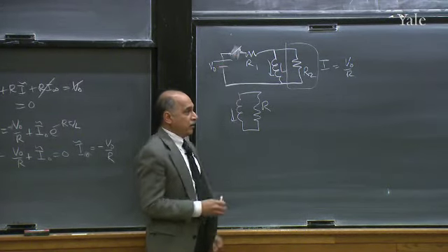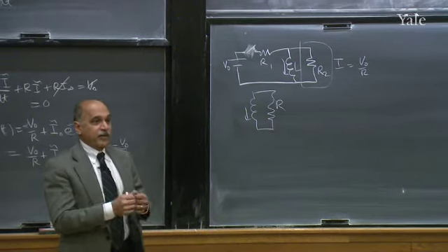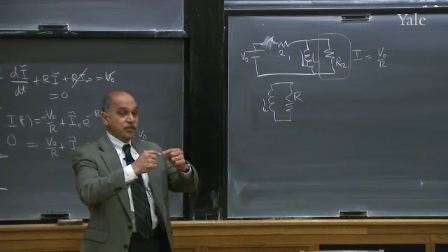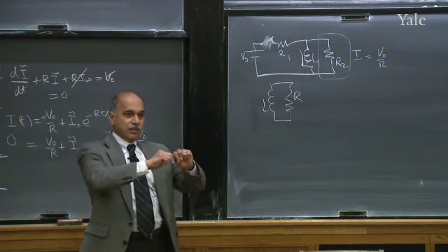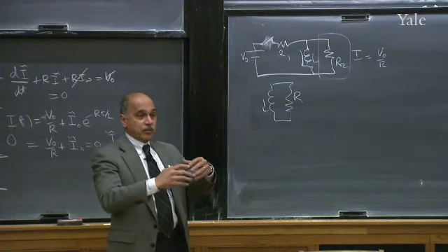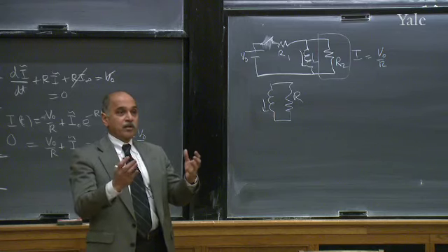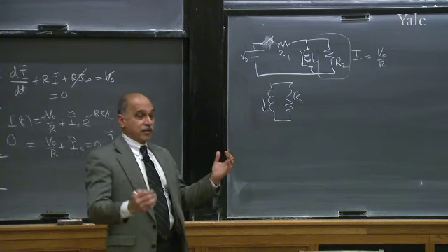The air is a path with very high resistance. That means, by and large, there are no free carriers in the air. But if the two tips get really charged, just like you said, there will be an EMF that will pile up charges. They're waiting to jump the gap, and eventually they will polarize the air, which is electrically neutral, into plus and minus parts. Then the minus will go one way, the plus will go the other way. You'll recognize that as a discharge.